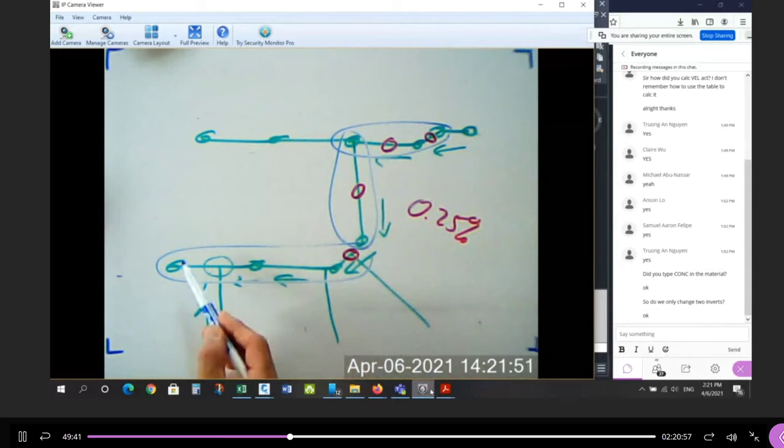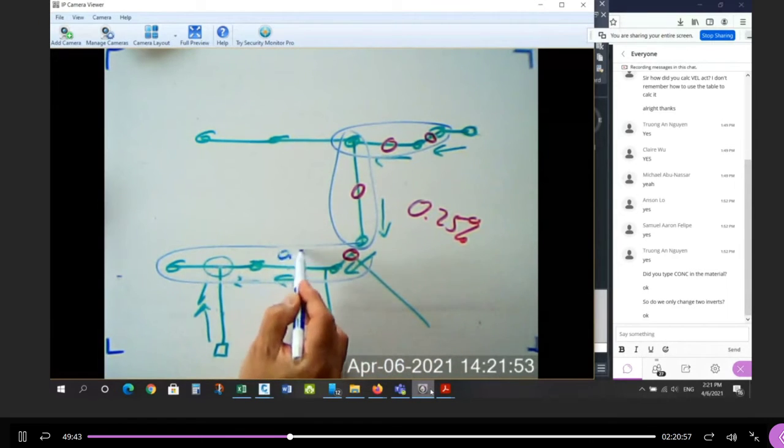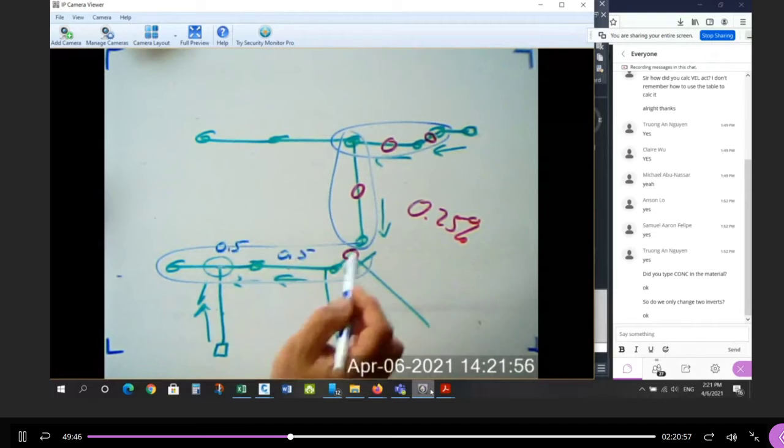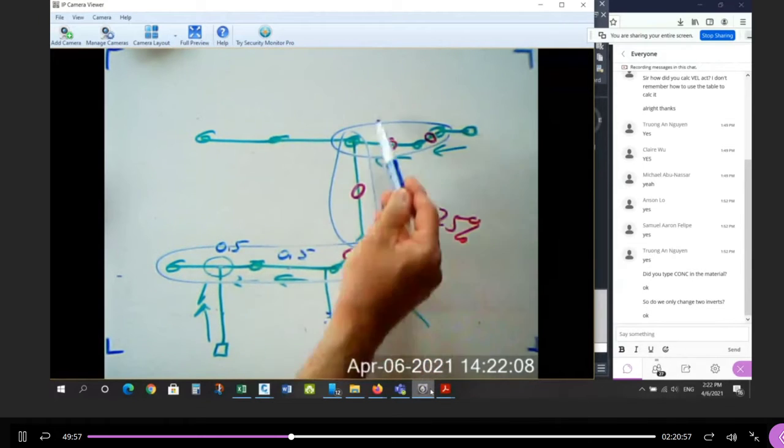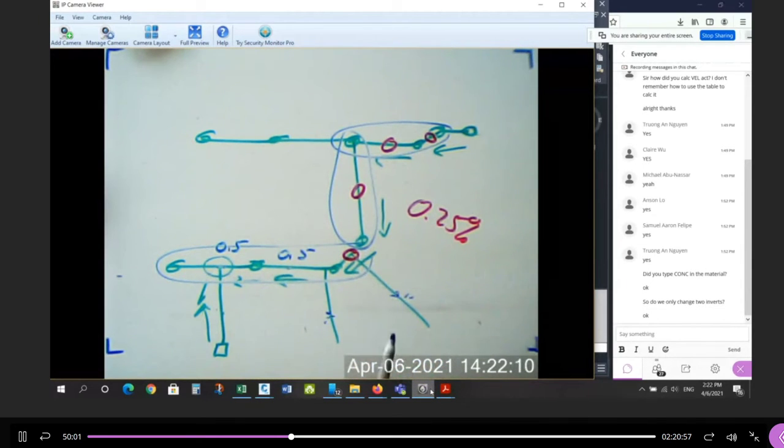We're pushing this whole system down even though these two don't change slope. These are still 0.5%. This one's still 0.5%. When you do that, you'll fix most of the issues, except for these last two on the southeast corner. Then these, we have to raise them up to match. And that's the last fix. So it's a combination of pushing the sewer down and raising the rear lot catch basin leads up. And that'll be a solution that'll work, together with that frost protection. Okay, don't worry about detailing the frost protection, just get the inverts of the pipes correct and show it properly in profile.